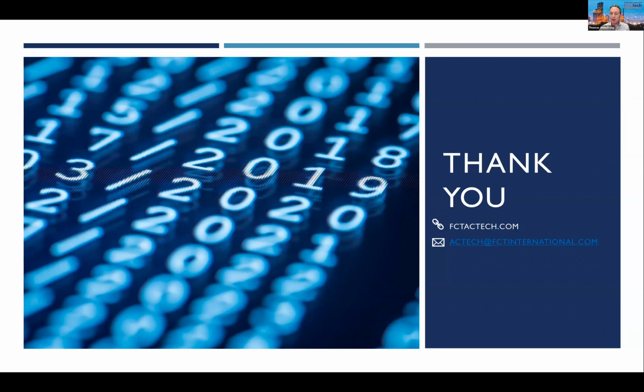Got it. Okay. And then I guess there's a question on maintenance: what level of maintenance is required? I see that you contain it inside a kind of closed, encased box. Yes, the box itself is quite protected, good for moderate moisture and a temperature range between -10 and +40 degrees. What I recommend is maybe to put a roof on top, or in southern countries a little shack around it with a very basic aircon to be sure that the analyzer can run under these conditions. The weekly maintenance is maybe 20 minutes for an experienced person, and it's mainly a cleaning and checking task.